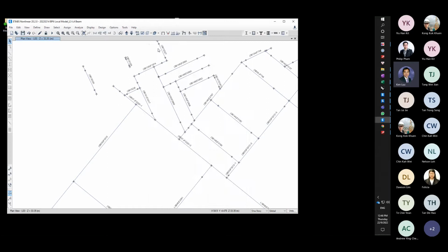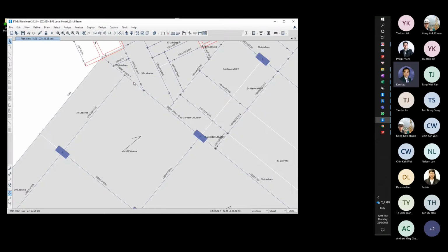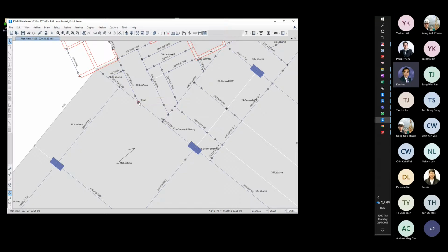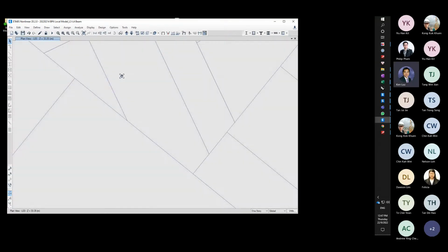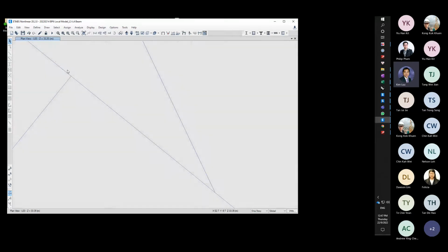You see, sometimes we have to mesh one beam into many beams like this. So this one is considered one beam, but because of the meshing problem, we have to mesh it into two beams so that this shares the same node with this. So to deal with that, we will try to put this symbol.